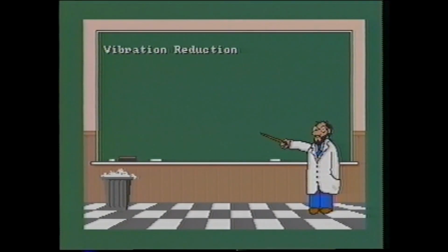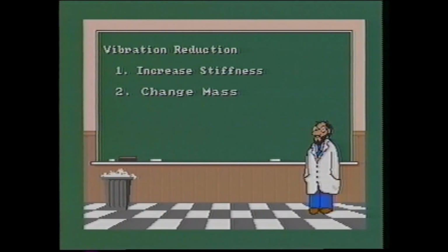Now that the vibration's character and the offending roll has been identified, we can attempt vibration reduction. Increasing the stiffness of any member that undergoes a large relative movement can increase natural frequencies and reduce vibration amplitudes. Strategically placed gussets from a vibrating member to a nearby stable member is often the most economical solution if feasible. Doubling the mass of a member that vibrates severely can cut amplitudes in half. However, natural frequencies will also be reduced. Another approach, though more difficult, is high tuning by reducing the mass while maintaining the stiffness of a vibrating member.